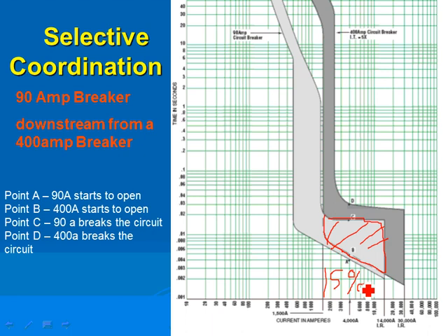But that will cover you. The only time this will trip is if you have a sub panel right next to the main panel in the same room, and you went inside the panel on the load side of a 3-pole 20 amp circuit breaker, and you tied the load side phase A, phase B, phase C together with a wire and a wire nut, and flip that switch. You could trip the main.